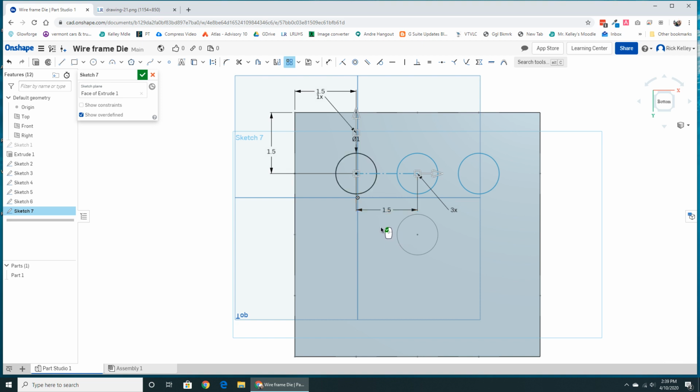Okay. Now it's showing me that little mouse symbol with a green check mark on the left mouse button. So click, and okay, it is now happy. We could mirror that or copy that. Let's go ahead and mirror it. A line from the midpoint. Where? I can see it wants to snap there, but it's not showing me mid. That makes me a little nervous. So, oh wait, I just saw mid. There's mid. Okay. Run straight across, and now we can use that perpendicular without fear.